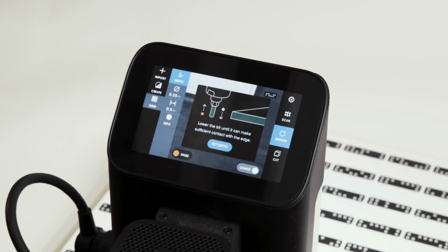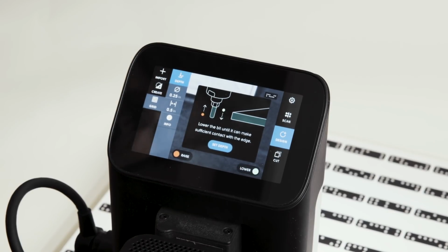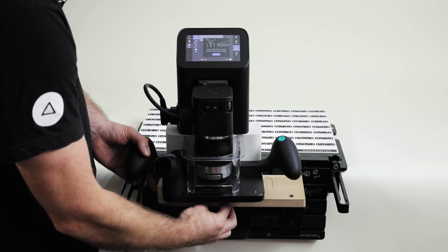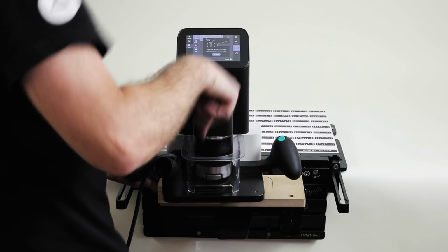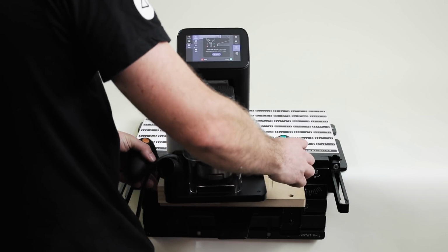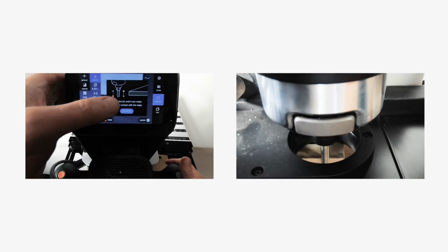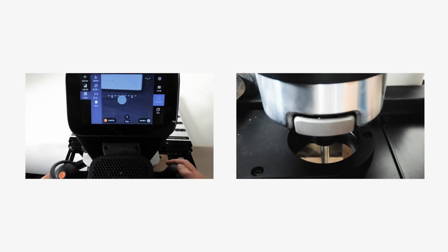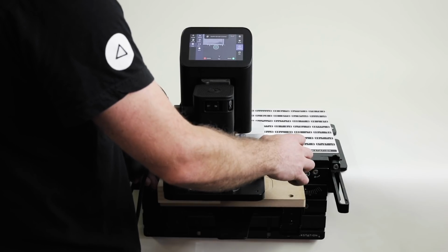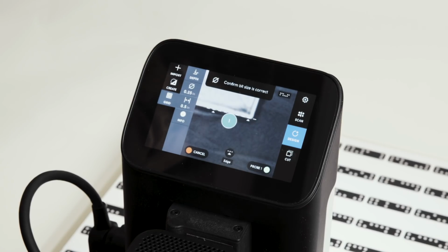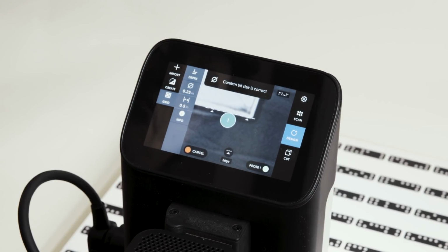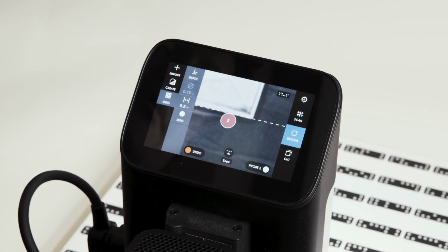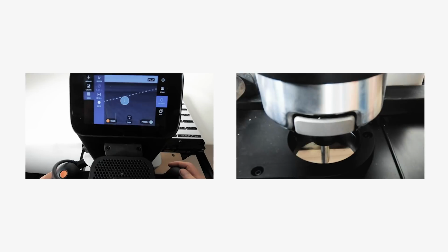Lower it down. We're going to move to the right hand side, and we're just going to make sure the cylindrical part of the cutter is down below the top edge of the surface. So we can confidently know we're measuring exactly using a cylinder. So set depth, same concept applies here. Very light pressure against the surface, and then that guarantees we get an accurate outcome. So I can feel it touch. I'm not pushing. Probe once. And then I'll move to the far end.